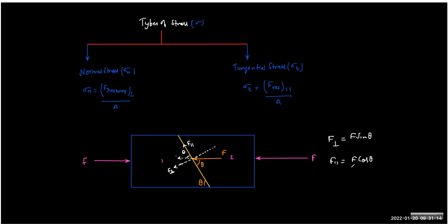Internal force. Correct. So the first thing you need to remember is that in the FBD, the F must be internal. It cannot be an external force. So when we solve questions of stress, we only consider the force which we can see developing there by drawing the FBD. So you cannot get the internal force unless you draw the FBD.